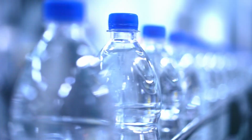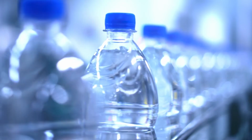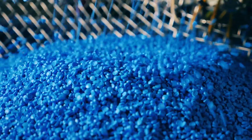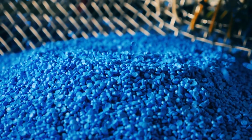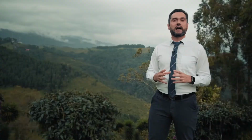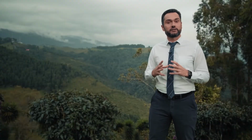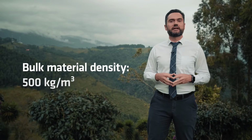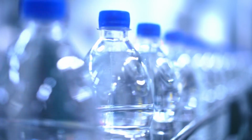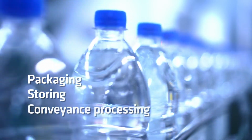Let's take a deeper analysis on the material characteristics to produce this massive amount of food-grade plastic packaging. Polypropylene pellets are a material with bad air retention or high air permeability. They have a medium weight and big particle size. Their bulk material density is 500 kilograms per cubic meter. The petrochemical plants produce the polypropylene pellets, and the plastic processing plants use the pneumatic conveying lines for packaging, storing,